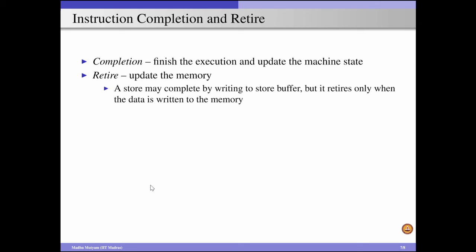So as a result, we'll write all the contents of these store instructions to the store buffer as long as the store buffer has enough entries. If the store buffer is full, then we have no other option. We have to take control of the memory and write the data from the store buffer to the memory, so that we get some free entries in the store buffer, and after that again we can give control of the memory to the load instructions if there are any load instructions waiting to be serviced.